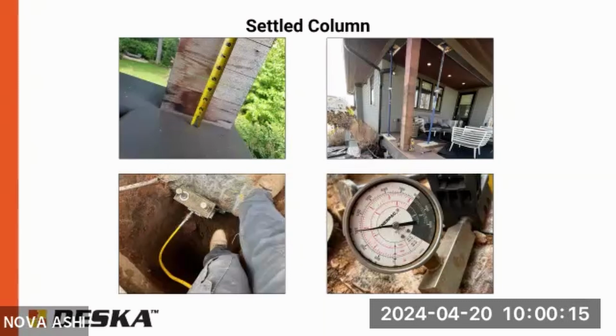When they ask me, why does this happen? I usually tell them, I'm not sure, but it could be that they built this slab on top of the fill, right? After they cut the hole or made the hole for the house. They used to put trash and everything else around the building site in here. They put the dirt on top, and then they did this slab, which is now obviously subject to the gravity, et cetera. And then I tell them to get an engineer because I don't know how to fix it. I can't tell them how to fix it.